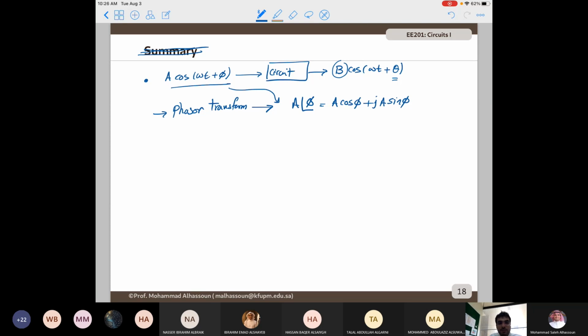Instead of using real numbers, we use complex numbers. It might look at first glance as if we were complicating the way of solving this problem, but in fact we are simplifying it. We saw last time how this simplification was achieved when we solved problems on finding Thevenin and Norton equivalent circuits, as well as source transformation.